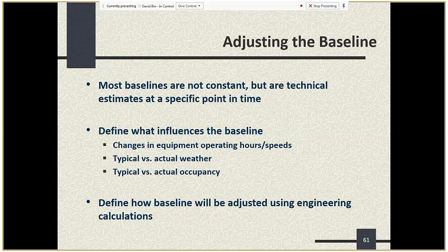And when you do that, and this is the ironic part, whenever you do an option C type of approach where you try to use utility bill data, you actually never can just use utility bill data. You have to run around and look at all the impacts on that meter, all the additional loads that could have influenced what that utility meter is reading.